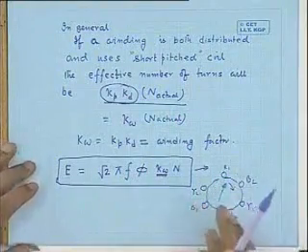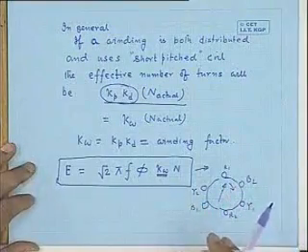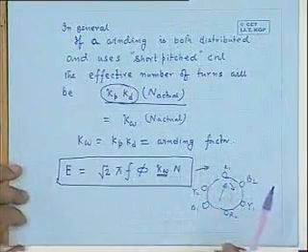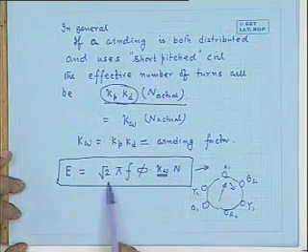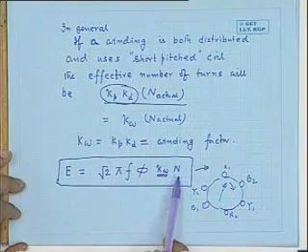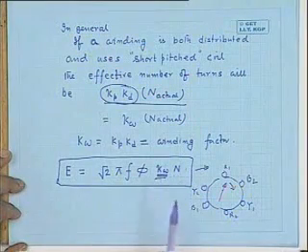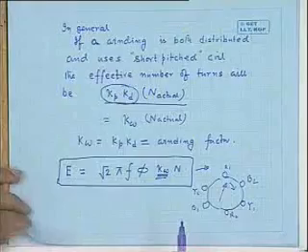This you just keep in mind. I will once again point out when I take up a somewhat realistic winding of three-phase machines. But with this background, I can now start the induction machine. So in rotating machines, you should remember that the actual number of turns physically counted alone will not be in this expression. It should be properly corrected because of the distribution of the coils.